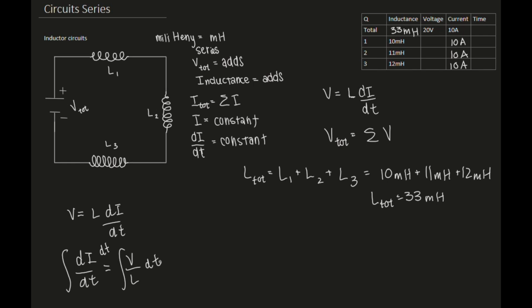The left side becomes the current in terms of time, some function of time, which is then equivalent to V over L times t. Now you might be saying, because this is an improper integral, do I have to include a constant there, plus c, because it's not bounded? I don't, because before I hook it up to the battery, there is no initial current. So my initial current is 0. I could say plus c, but c is just 0, so I don't need to include it.